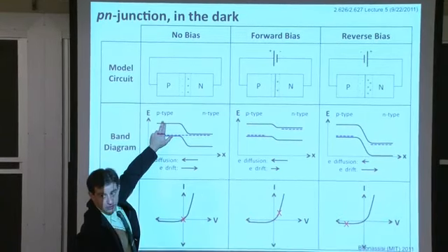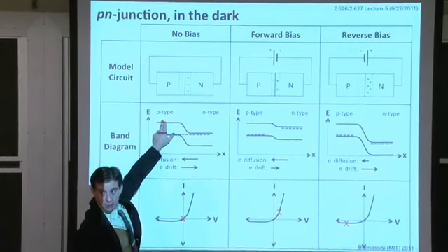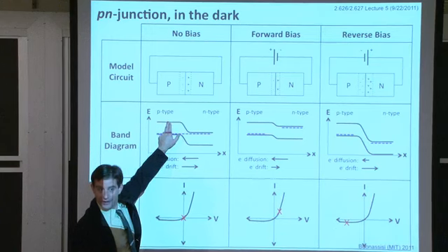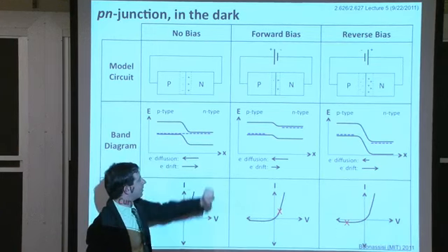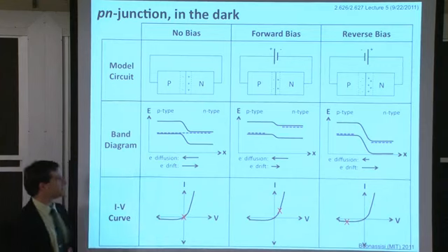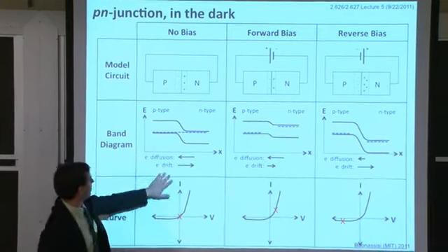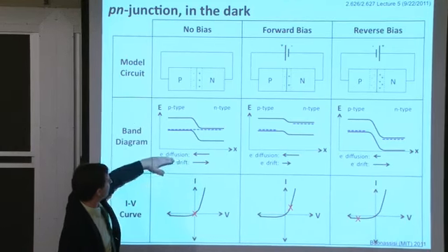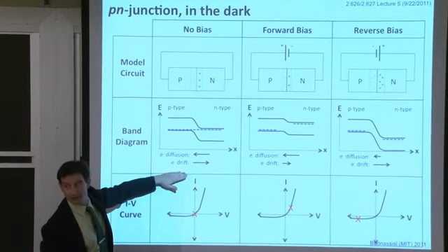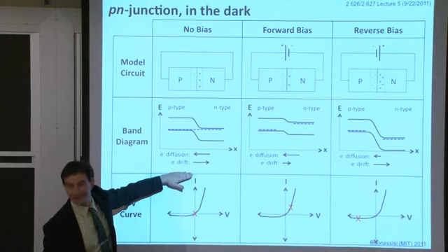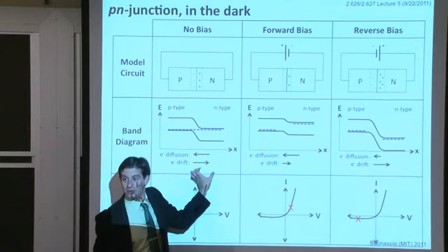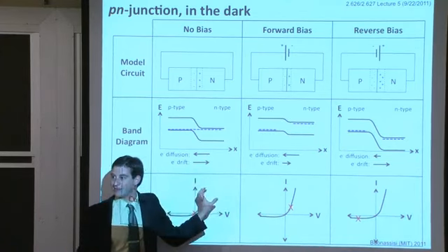What will happen to those electrons now that they're in the conduction band? Where will they want to go? To the right, right? Okay, so what you'll do is set up what's called an illumination current. Notice now at the bottom of the second row here, you have electron diffusion, electron drift, and IL current. IL stands for illumination current. So you have a third arrow here that will have to be implemented in some way.